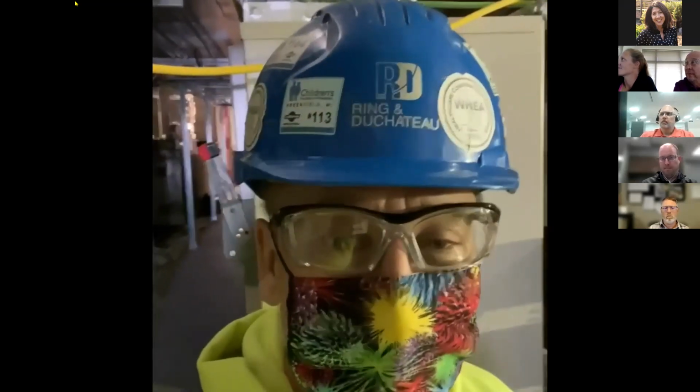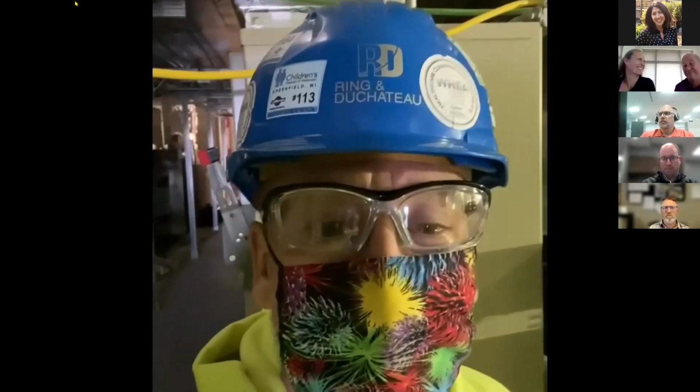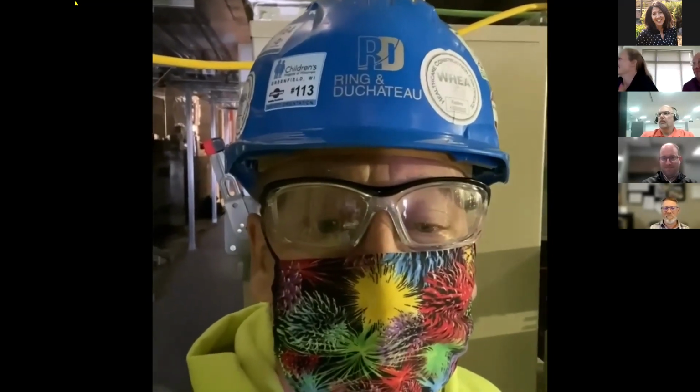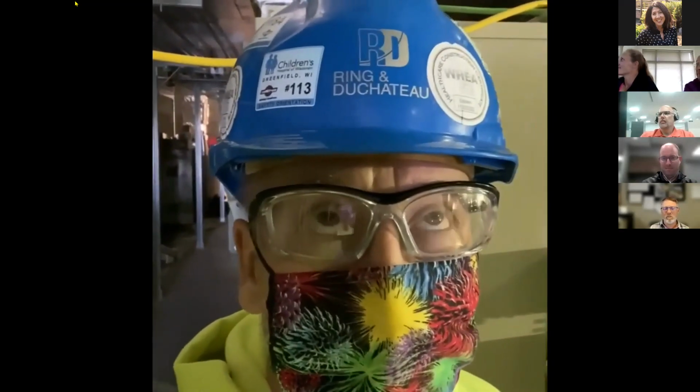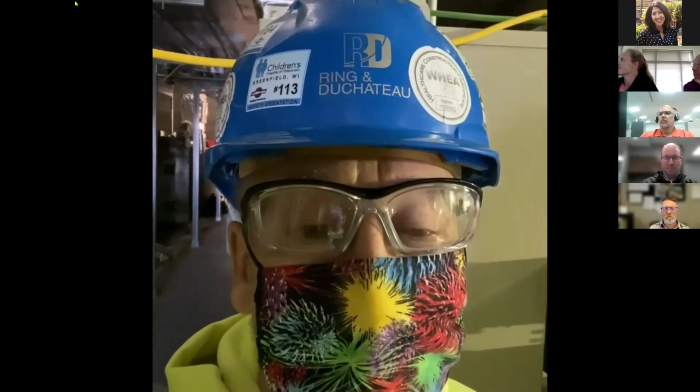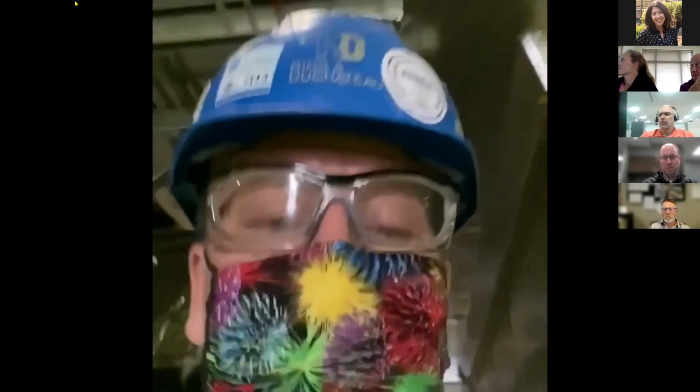Hey there, me again. We're going to test now, along with the aid of the fire alarm contractor, one of many means of shutting down the air handling unit with the duct detector, which is located over there. But the test switch is located over here.